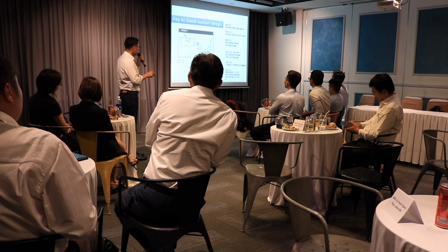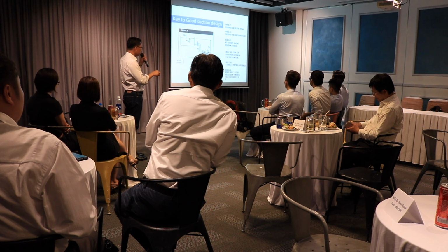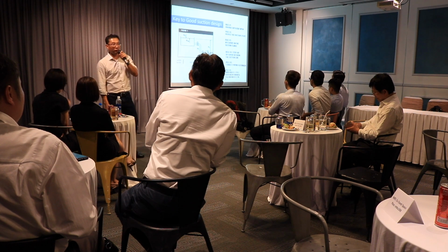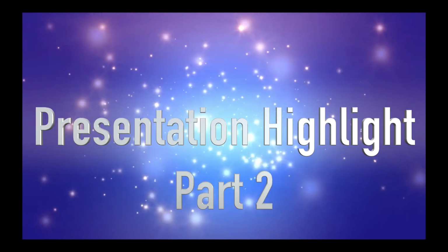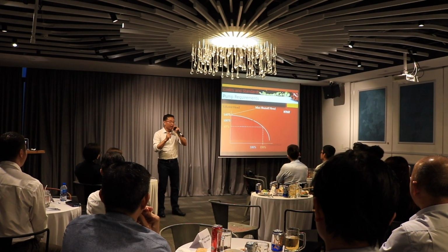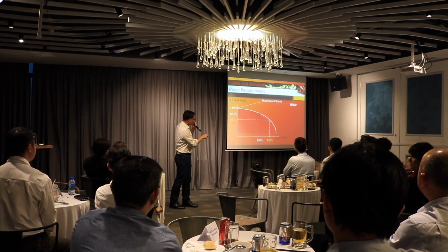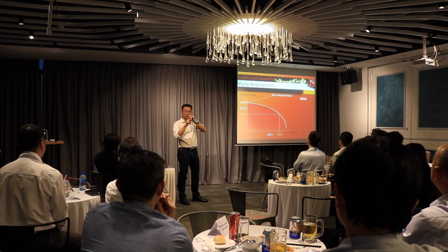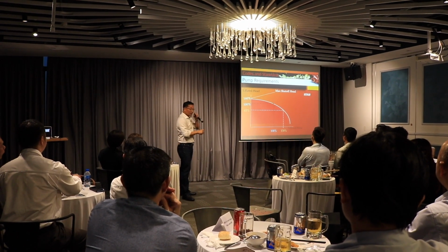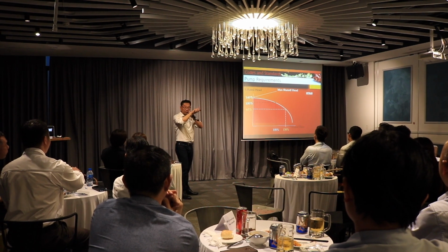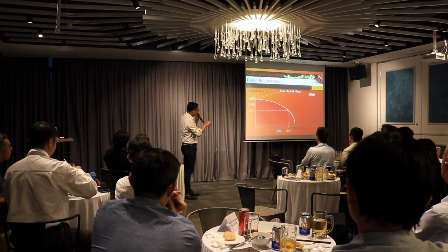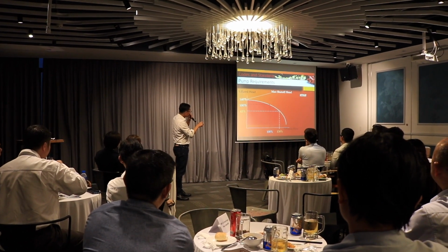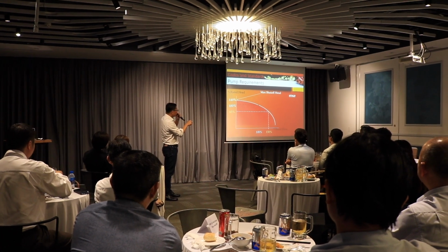Rule number 6, when rules 1 to 5 have been ignored, follow rules 1 to 5 again. I can operate in the range between 100 to 150. That's the NFPA 20 requirement. Okay? Now, the condition that happens: after I select the pump, the shut-off pressure must not be more than 140% of my rated.